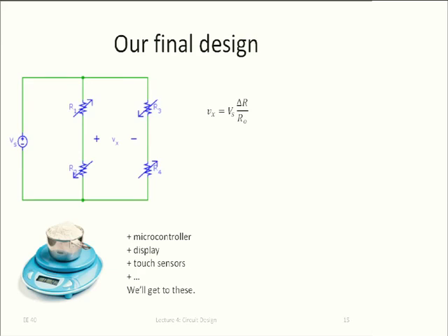And again, we can do a bunch of math to figure out what Vx is. In fact, it's quite simple. How would we find out the voltage Va? How could you find out what Va is? Yeah. It's just V by 2. Isn't it? It's just voltage drops across R2. Yeah, exactly. So the circuit would be a voltage divider, right? We really can treat R1 and R2 as a voltage divider. They divide voltage Vs, and so Va, if we, let's say, call this ground, then Va, which would be this voltage, right? Va would be equal to Vs times R2 over R1 plus R2, okay?